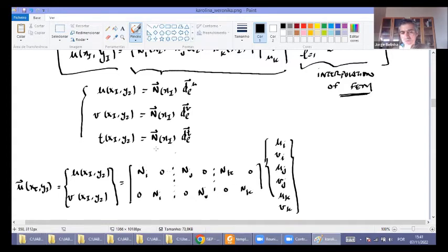If you make this, you'll see that this multiplied by that will only affect the u's first, and this multiplied by this will only affect the v's. So you'll get the u and the v. It is the same as writing these two separately. The finite element method likes everything combined, it does not like separated variables.